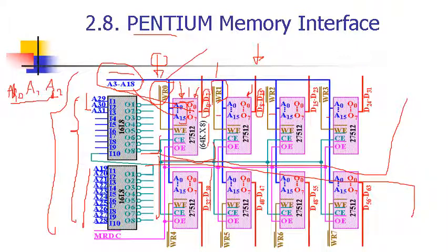If all write strobes are active at a time, okay, so you're writing 64 bits at a time, you're taking D0 to D7 from your data bus, write them into your 0 bank, D8 to D15 into your first bank, D16 to D23 into your second bank, and so on till you write your D56 through D63 into your 8th bank.